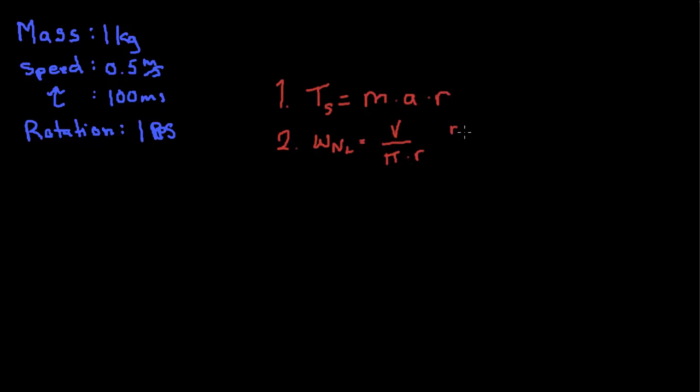Remember, this is in radians per second, which you've got to convert. And 3, of course, the rotational speed of your robot, which is given by r is equal to the linear velocity of your robot divided by pi times the axle length, given d here, between your two wheels, and that's in rotations per second.